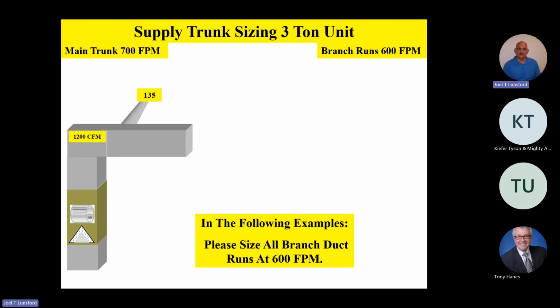Let's see how much we're going to need in there. I apologize, Joe. Would you repeat the question? Yeah, what size duct do we need for 135 CFM off this first takeoff? What size, 6 duct? Or 7. Okay, good, excellent. 7-inch, good. Give yourself a star. That is correct. So 7-inch duct is what I've got on my calculator as well, at 135 CFM.